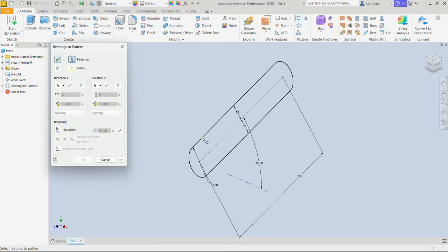The feature we want to pattern is this one, the direction. It should go along this path. And for the buckets we want 15 buckets, so I'll type that in here. And we want to say that for this distance, we want to define it with the curve length. So make sure it gets 15 of them. However it spaces them along that curve length, we are okay.